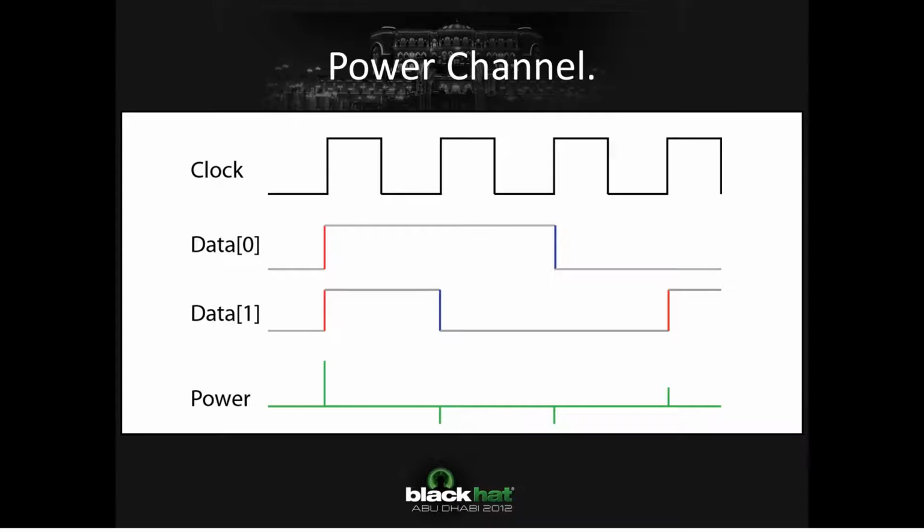It has a little bit of capacitance, so you set it to some value, and changing it to that value does take power. Once it's at the value, it doesn't take as much power to just keep it in that state. So every time we change, it takes power. This is why, as processor speeds go up, the amount of current typically goes up as well, because it's switching more often. It's changing data line states more often, which means it consumes more power.